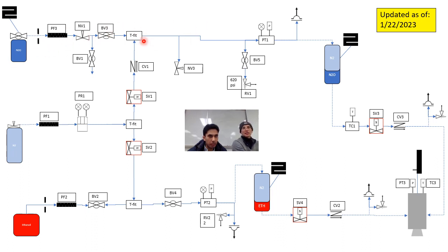So we're assuming BV3 is open, and that's what's going to start flow into that whole system. And again, it's similar to ethanol. It's going to be gravity fed, so it's coming down into the run tank, and eventually stopping when it hits solenoid valve 3. So it's all flowing down from this tank, filling all these, and eventually stopping in this run tank, ultimately stopping due to SV3.